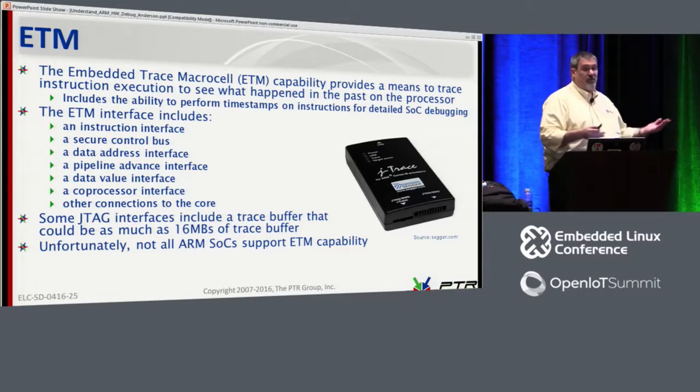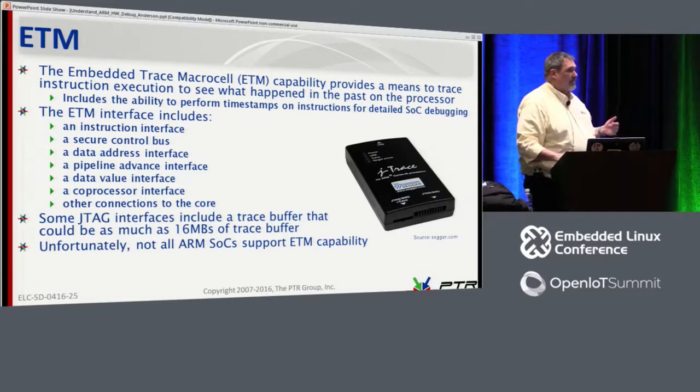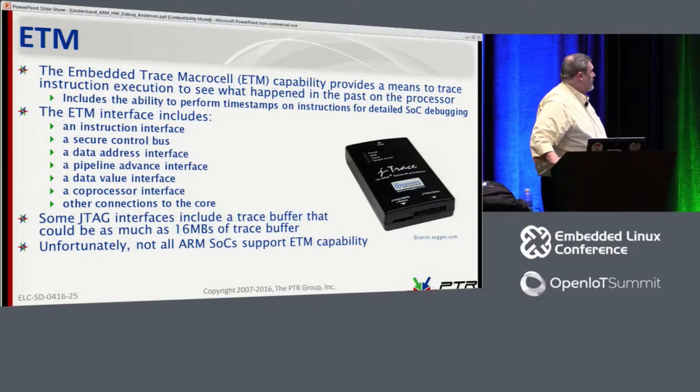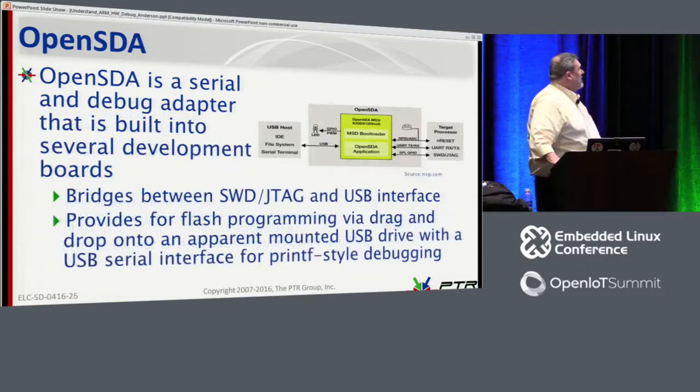So unfortunately, not all ARM SoCs support the trace macro cell option. So again, you have to look at your manufacturer and find out from their data sheets whether or not they have in fact included this capability.